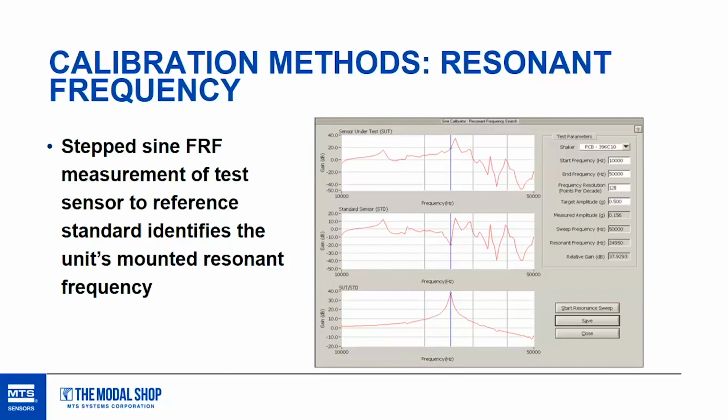So additional information that you get out of your sensor. Do you need to do this for a recalibration? Maybe, not necessarily. Oftentimes, if this resonant frequency shifts enough, you're going to see it in the low frequency data as well. So you'll see those frequency response bands get clipped when your sensitivity is pushed down enough or up enough due to a shift in the resonance. So they're really kind of hand in hand, frequency response and resonance. You're checking either the low frequency or the high frequency portion of that sensor's performance.